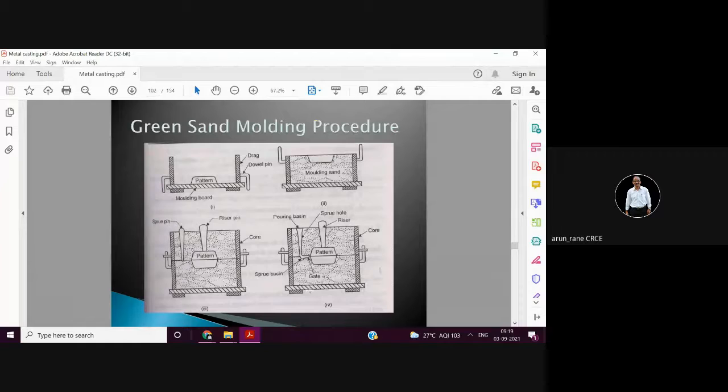So that's why in injection mold or die casting, you don't have a riser. But here the riser is essential because now 500 ml is required. You are pouring 600 ml. Some part will go here, and the excess molten material will rise up through the passage which is called the riser. So this riser, gate, runner, pouring basin, these are all waste, scrap, which has to be chopped off once the casting or the product is removed from the mold.